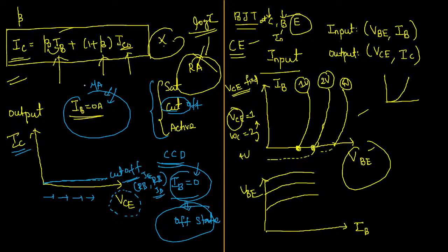Okay, let me keep some 0.5 microampere. Slowly we will be increasing it. Okay, sir, 0.5 is very less. Let us take some 3 microampere. Anyway, I am injecting some current. Now what will happen? If you are injecting the current, then I will be very happy. Your transistor initially will be in saturation region, then slowly it will be entering into active region. So this zone will become active. Let us break it actually. This is called active region now.